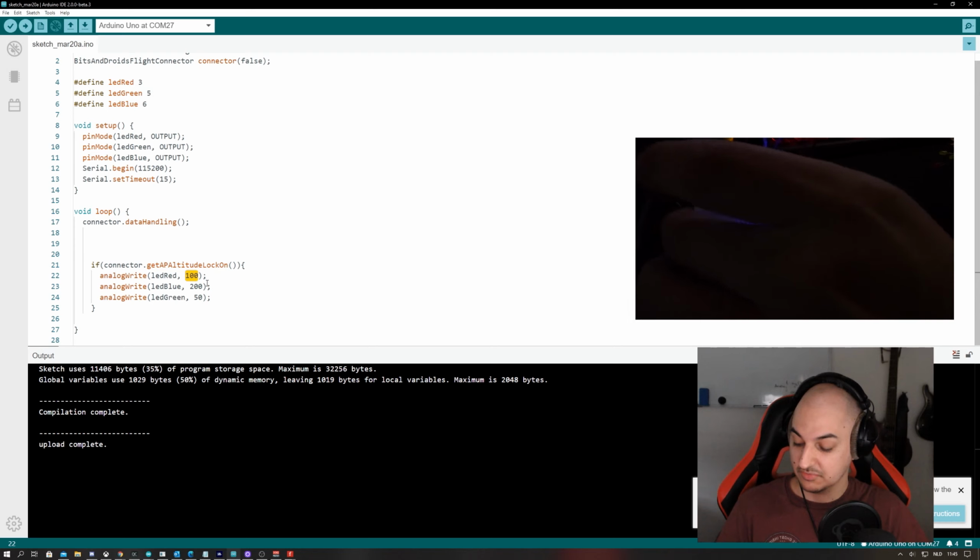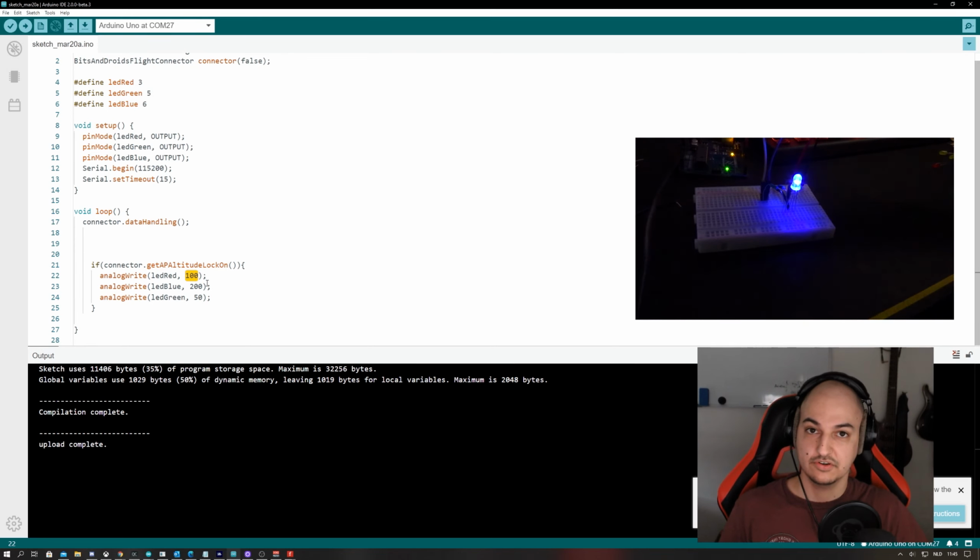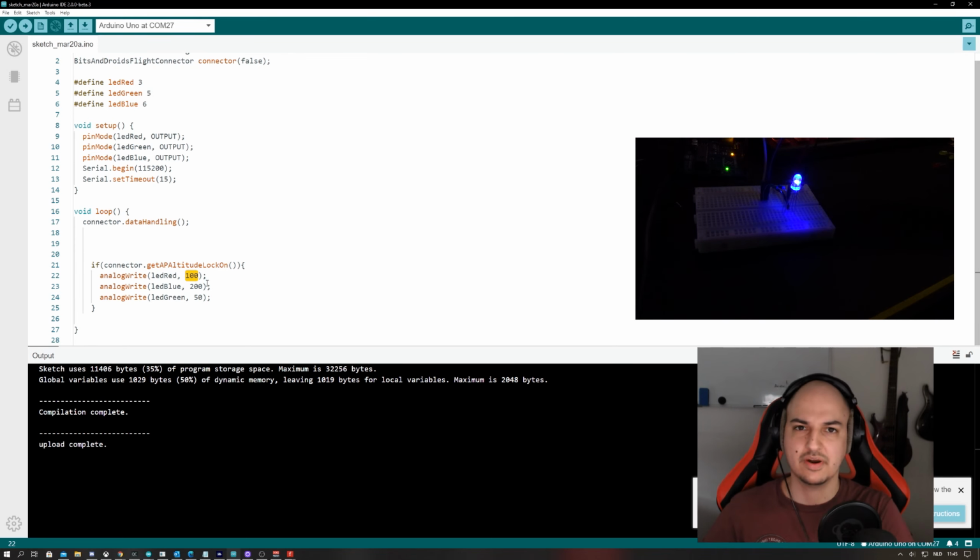Now this takes up 3 pins, so that's quite intensive, especially if you're using a Uno. Perhaps if you're using a Mega, you've got a larger range of pins available, so it's easier to hook it up like this. There are some options to reduce the pins needed by using some kind of chip, I2C interfaces, whatever, to really reduce the amount of pins needed to control LEDs.